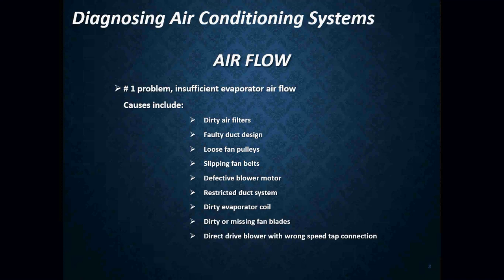But what's going to cause inefficient evaporator airflow? Well, it could be a bunch of things, really. Now, when we think about it, this is because air handling systems do not just suddenly increase or decrease air volume across their ductwork, okay? Now, airflow or air volume is calculated in CFMs. That is cubic feet per minute, CFM. Without some sort of outside help, that's going to cause that airflow to change.